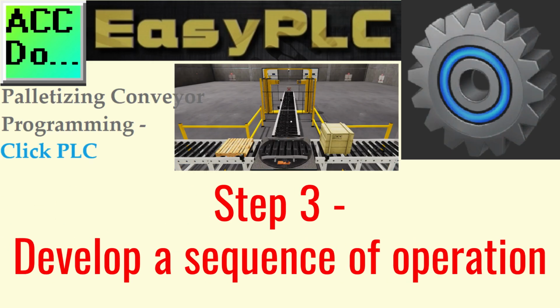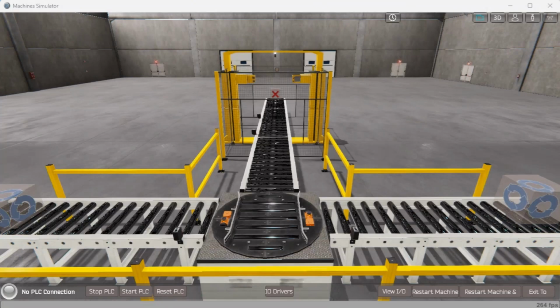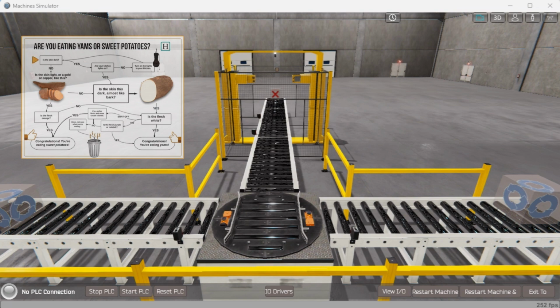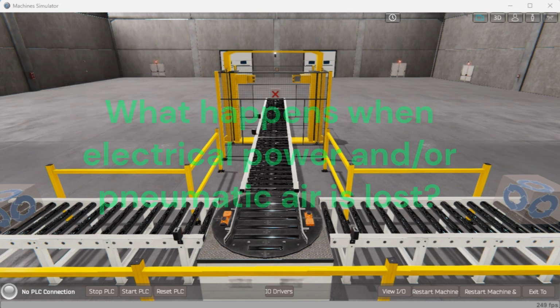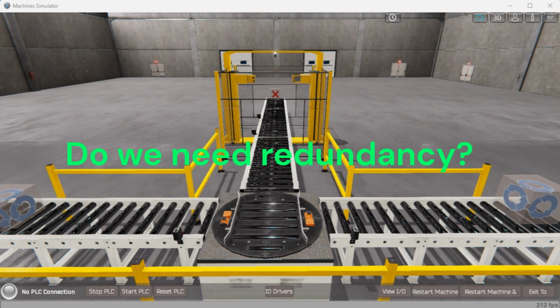Step 3. Develop a logical sequence of operation. A flowchart or sequence table is used to understand the process that must be controlled thoroughly. It must also answer questions like, what happens when electrical power or pneumatic air is lost? What happens when electrical input devices fail? Do we need redundancy?